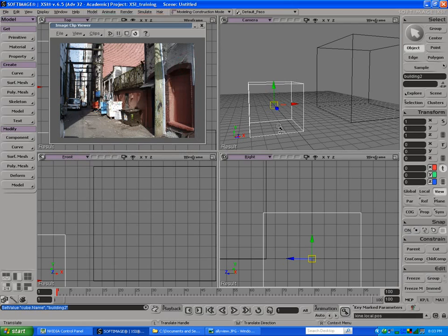There's several ways to move things and snap. I'll use snapping a lot. So one really cool feature is the temporary pivot. If I just try to snap this, I'd have to snap based on the pivot. If I hold Alt down and click on the corner, it'll snap that pivot to that position. Now I can use snapping tools to snap this to the right position.